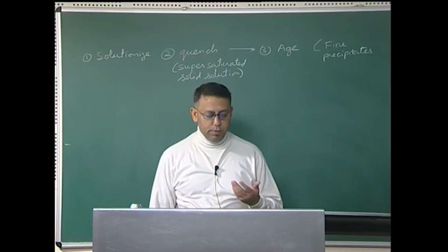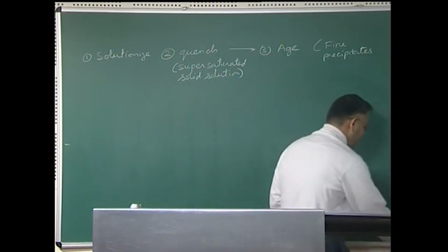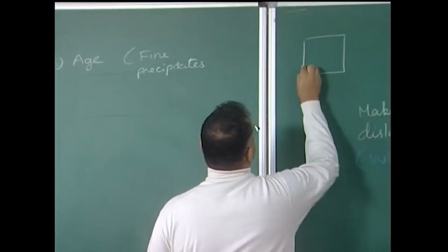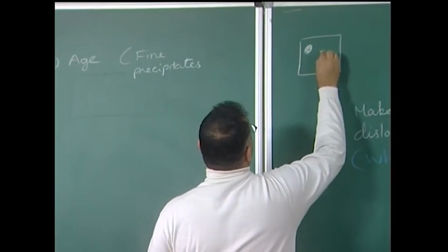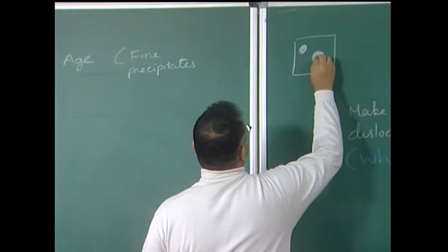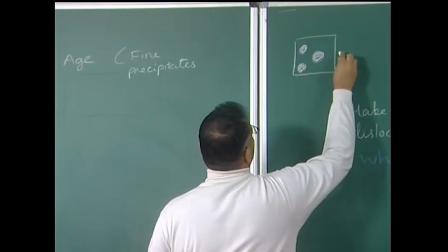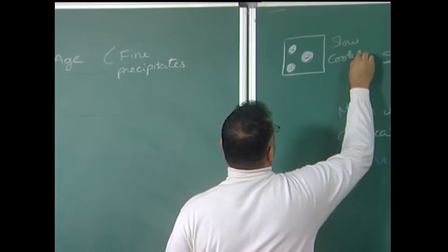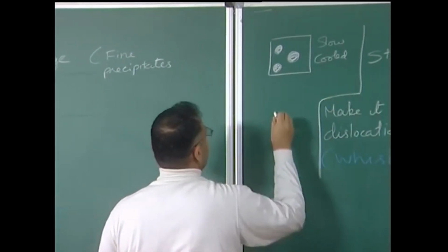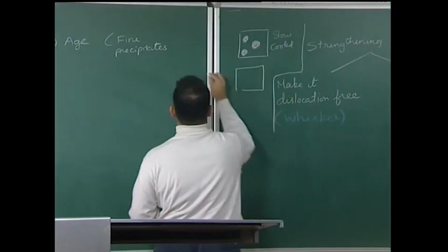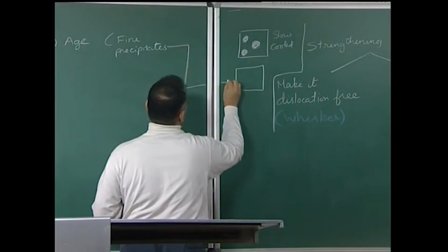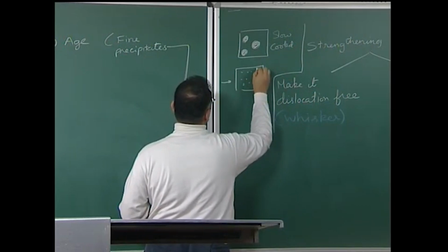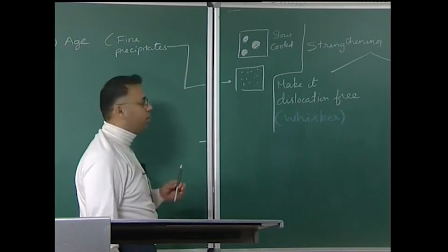That means the theta phase which will be produced would have a microstructure something like this. So, this is a slow cooled system, and we had already considered a microstructure like this before. Vis-a-vis, suppose I consider a system which has gone through this kind of a treatment, which will have a fine distribution of precipitates. Of course, the morphology of the precipitate will not be what I am showing here. This is just a crude schematic.